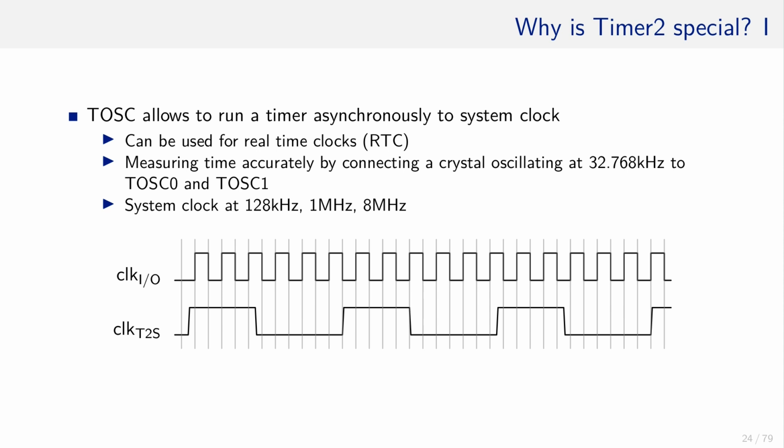However, what if you need an entirely different frequency, such as 122 kHz? In that case, you can connect a crystal to TOSC1 and 2 with the desired frequency of 122 kHz. Since a crystal needs 2 connections, 2 pins are required.